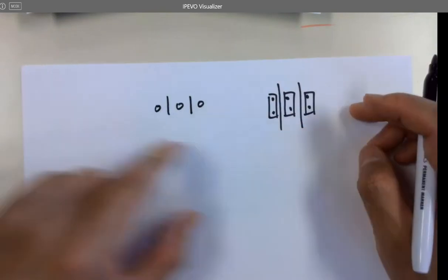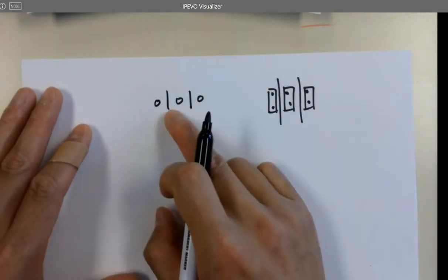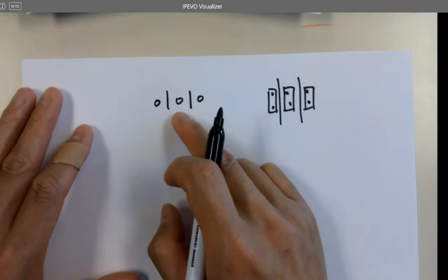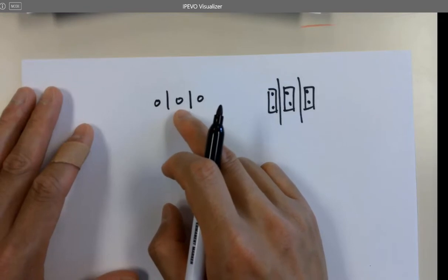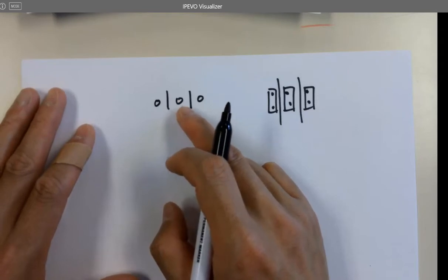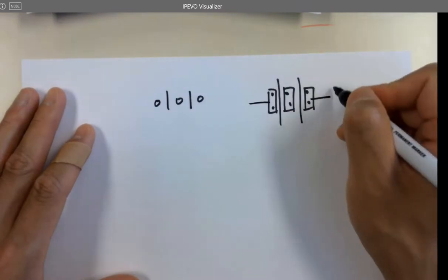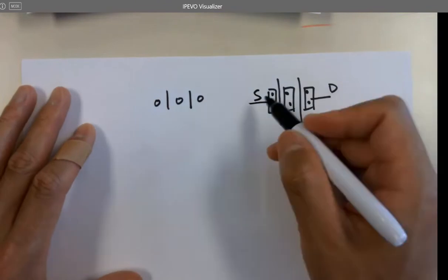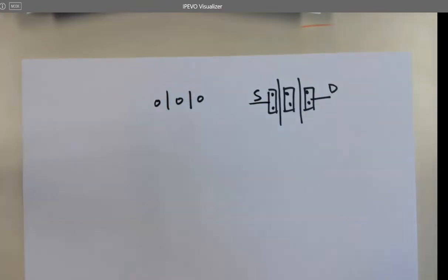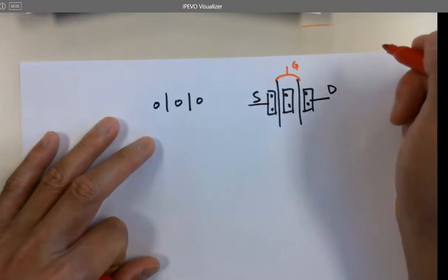Right? Equivalent. And now, if I combine them like this, how can I make these two PMOSes in parallel instead of in series? Just short the poly together, right? If you run current like this, and you don't do anything else, just directly run current. I just short these two gates, just turn it on, okay? You can turn it on, no problem.